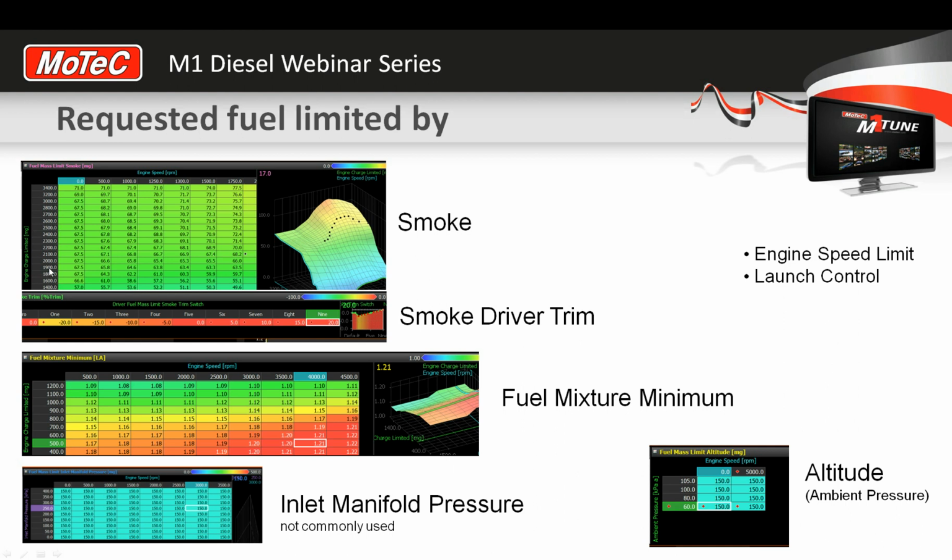On this vertical axis here, we can see we've got 2,000 to 2,400 milligrams of air. These are real numbers, from an Isuzu 3-liter, I believe. So this is how much weight of air is going into each combustion event, into each cylinder.